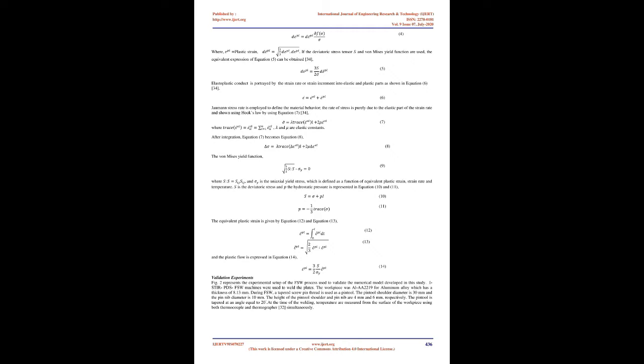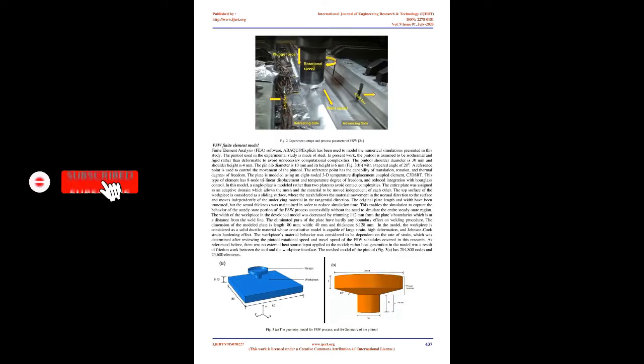Later work done by Sun et al. 29 developed a three-dimensional model which determined heat generation at the workpiece interface utilizing interfacial frictional pressure. The model computes interfacial frictional pressure directly based on the pressure of the material near the pintool workpiece interface and the von Mises yield criterion. The interfacial friction stress is then connected with the temperature. The interfacial friction stress decreases continuously with increase in temperature.